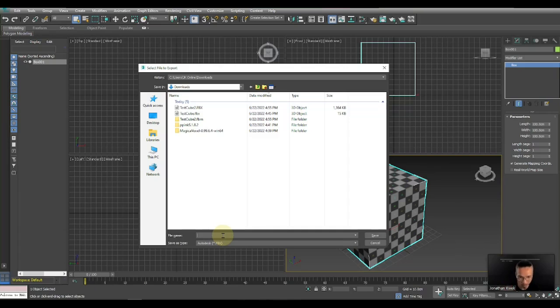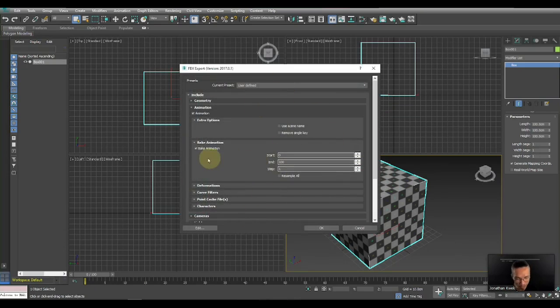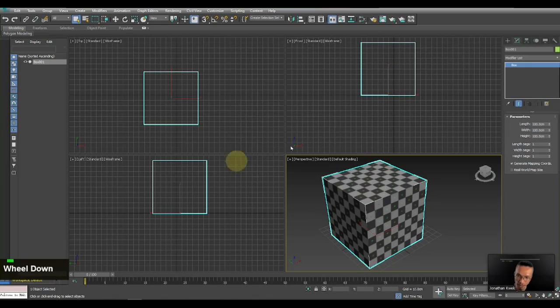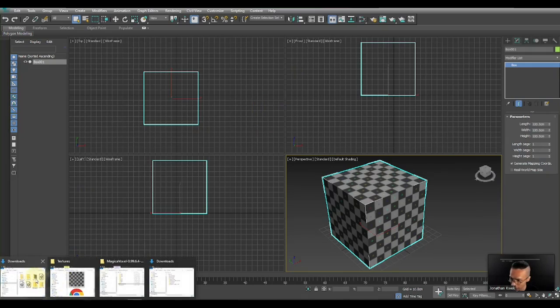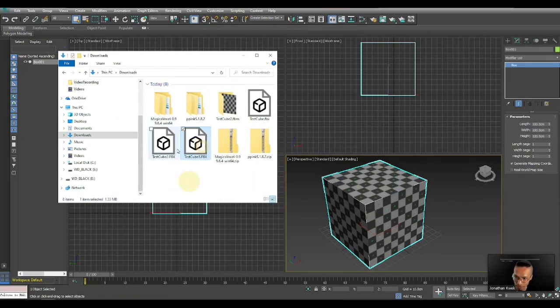We'll talk a little bit more about formats in a bit. So I'm going to export this, and they're going to ask for some settings over here. Generally, the default settings will work just fine. And then done. So this concludes your workflow in the DCC, the 3D digital content creation tool side of things. From this process, it gives you an FBX file that you can now bring to your game engine.